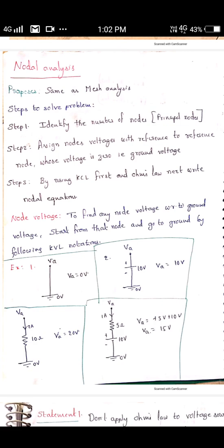If you want to know the branch voltage between one node and another, suppose one voltage source is there in the network and its magnitude you don't know, but all the remaining branch voltages you know. Then to know that voltage, start from the positive terminal and go to the negative terminal. While calculating each branch voltage from positive terminal to negative terminal, if you consider any loop, you will get the same answer. You have to get the same answer.